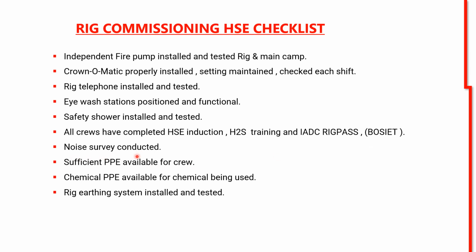Noise survey conducted, sufficient PPE available for the crew, and even some extra PPE should be at the rig site for the visitors. Sometimes some persons come for audit purposes, for inspection, for installation of new equipment. Sometimes the service company or third party also come, so extra PPE should be available.